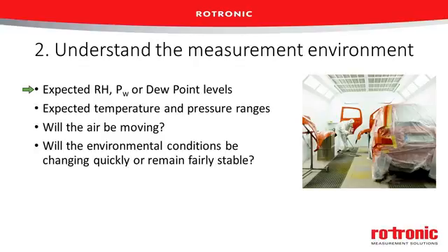What would be the dew point level? If your parameter that you're interested in is dew point, then you should know what kind of a range to expect there as well. PW is the partial pressure of water vapor, and that means you may have to know what is the range of the actual mass of the water vapor in the environment you'll measure.